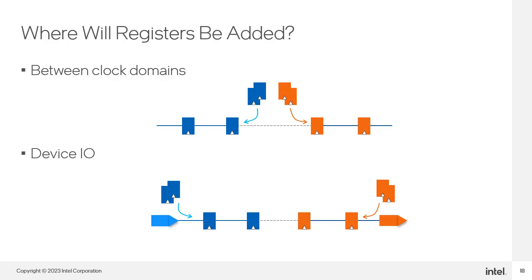When adding registers, if you had to burrow down deep into your RTL to add the register stages at specific design points, that would really mute the usefulness of the recommendations. So, fast-forward compile will typically add the registers at more easily accessible locations in the design, such as in between clock domains where you may already have synchronization registers, or at the inputs or outputs to the design. This is assuming you do not have internal endpoints such as asynchronous clears that prevent registers from retiming further. If this is the case, then hyper-retiming may also be required for that particular step.